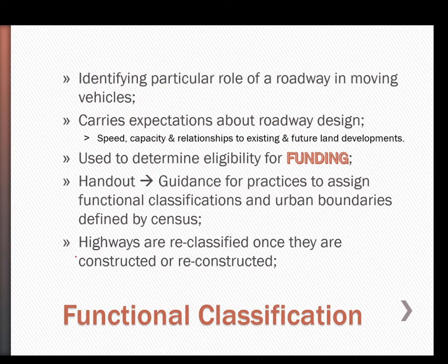So function classification, let's define it now. It identifies the particular role of the highway in moving vehicles. What's the role? Is the role the main direction, the main mobility? Is the role to give access, or is the role to collect? It carries expectations about roadway design.